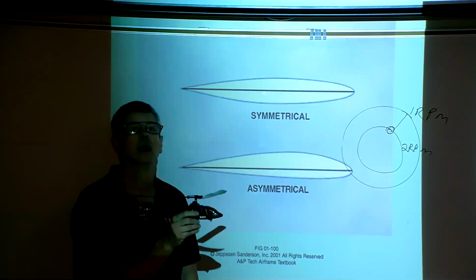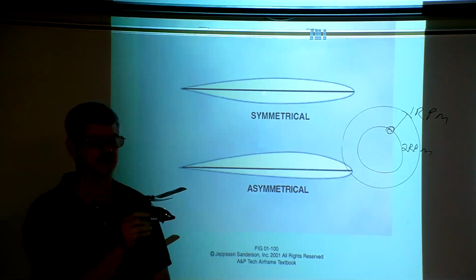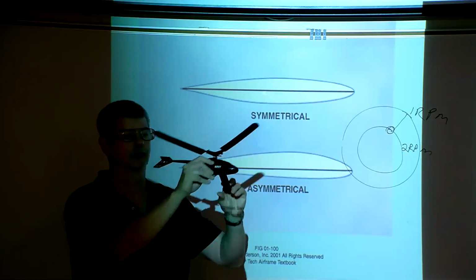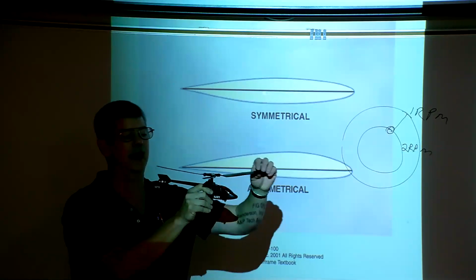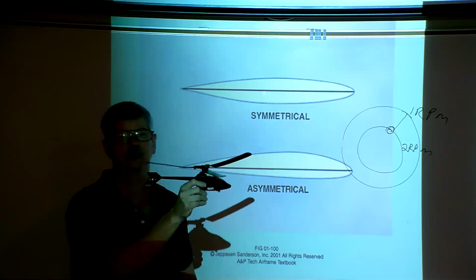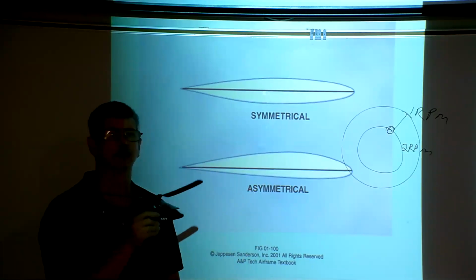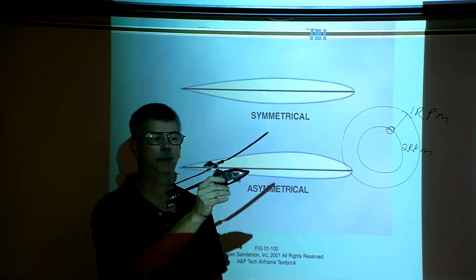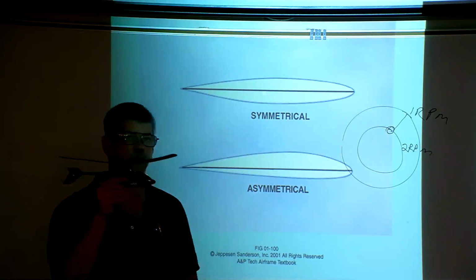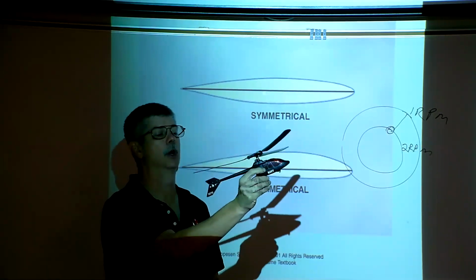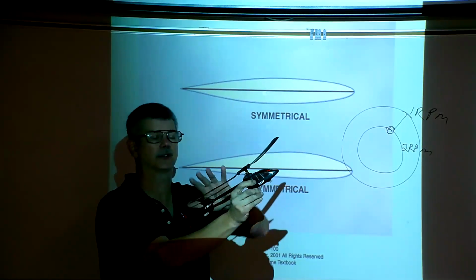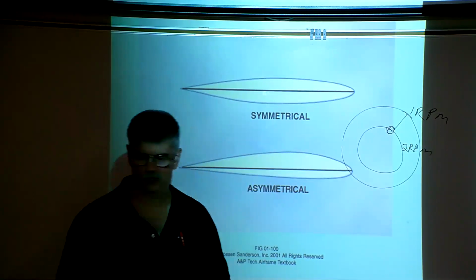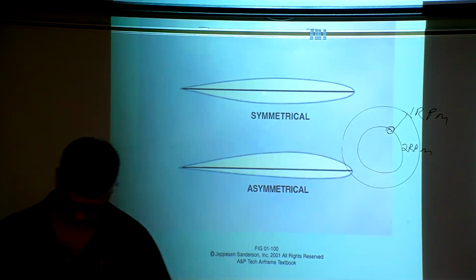Okay? Now, because of precession, the effect is not to roll the aircraft over to the left, but acts 90 degrees towards the tail. So in a retreating blade stall, does the nose go up or down? And the answer there is that the nose goes up because we lost the lift at the tail. So the helicopter would tail down or nose up.